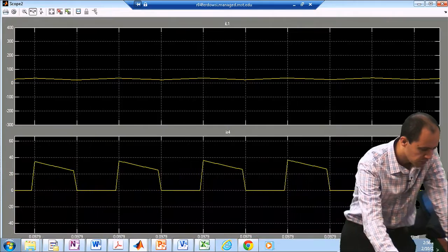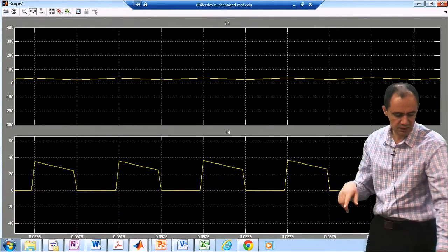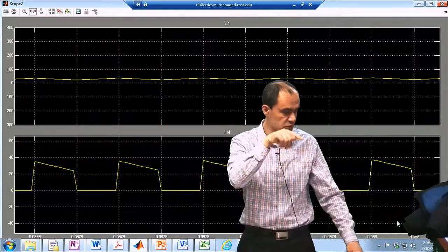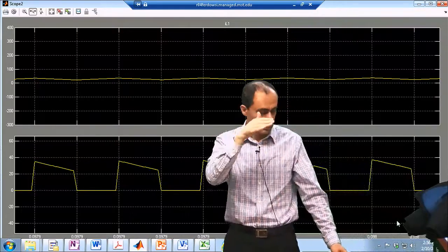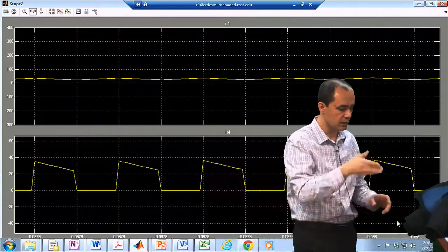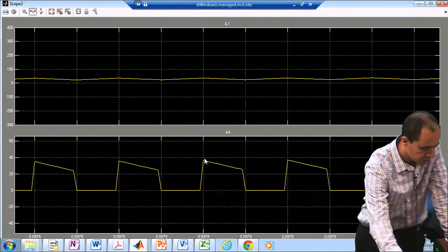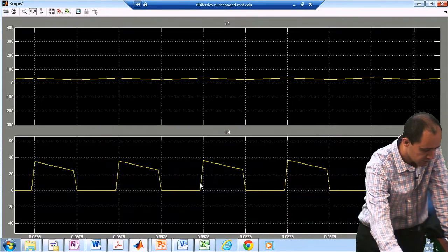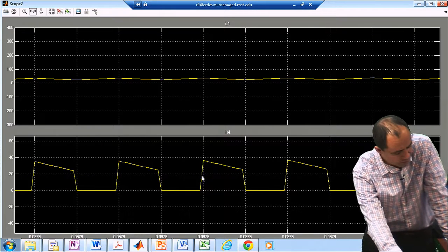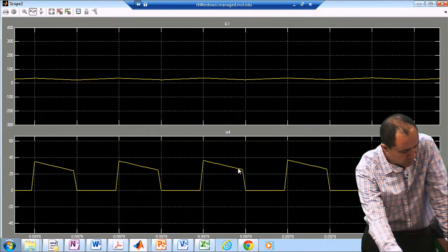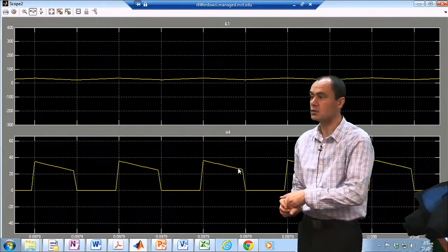Again, that ripple is there, and you can see that it is the classic waveform for a switch. It jumps from 0 to a peak value of I max, then ramps down to I min, then jumps back down to 0. This ramp is not supposed to be there. This is basically because the time resolution in MATLAB is not high enough, and this ramp is not supposed to be there. So the ramps are either 0, and the declining ramp is because of the value of L2 basically.